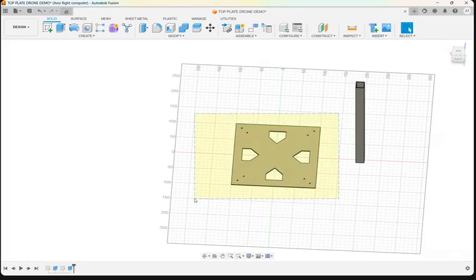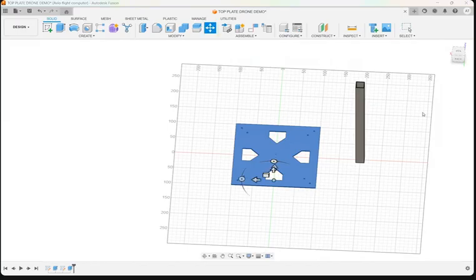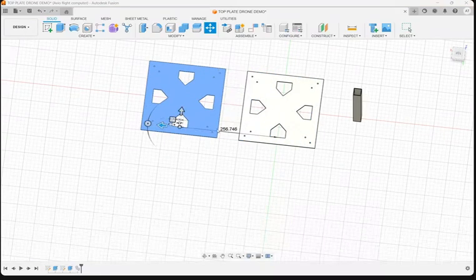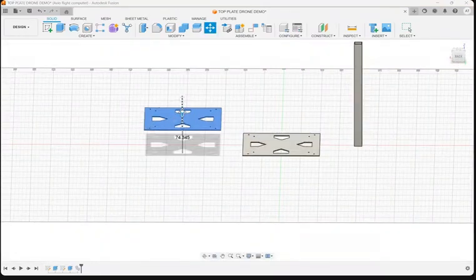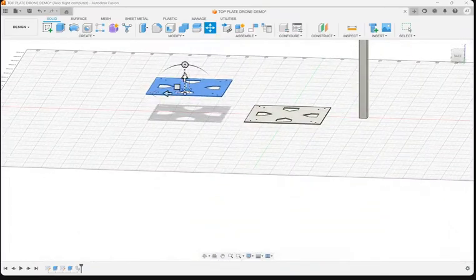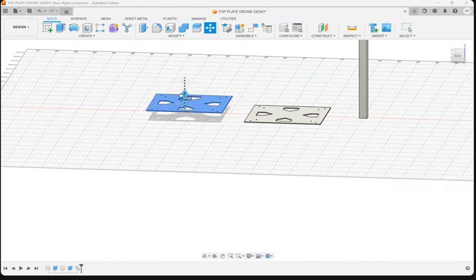So what I'll do is right-click and select it. I'll click on the top icon. Here there is a move/copy option. If I press this select item checkbox, I can move this somewhere. Holding these arrows, the x-axis, y-axis, and z-axis, you can move it in any plane. Over here, you can see how much you have moved in which direction.